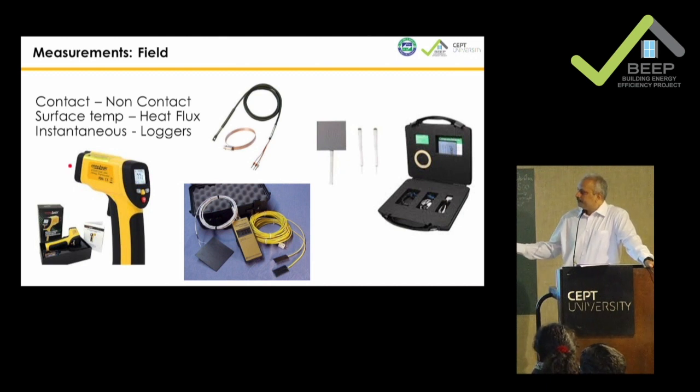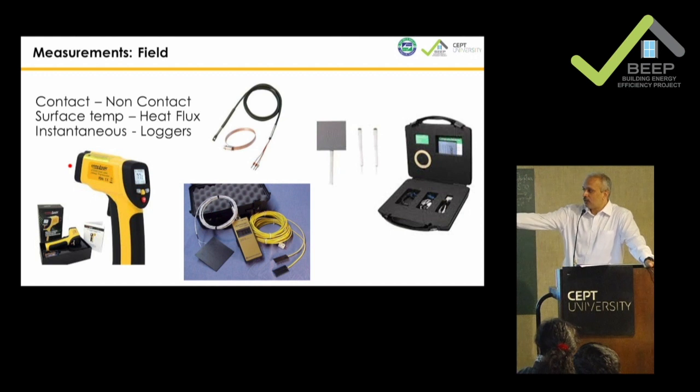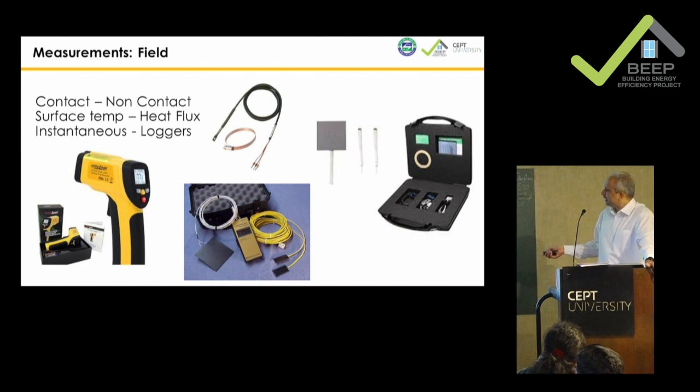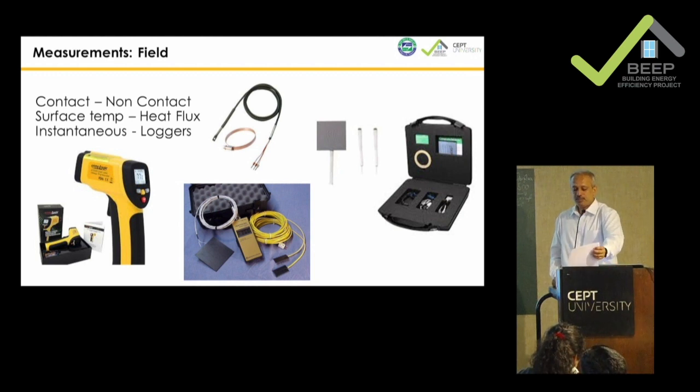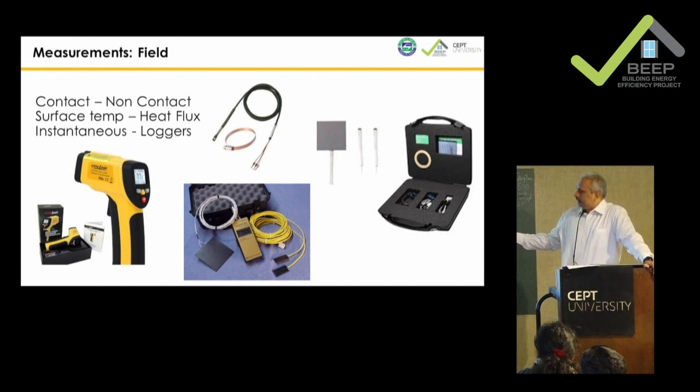What you are doing here is more instantaneous. Right now, what's the surface temperature? But if you need to keep logging it every hour, you need a logger attached with it, okay? There are new techniques where people also start looking at on-site U value measurements. I haven't seen it functioning, and I have seen two sides of various opinion about it. How well does it calculate U value? But these ones try to help you understand heat transfer, versus some of these kits straight away give you U value. So overall thermal heat transfer values.